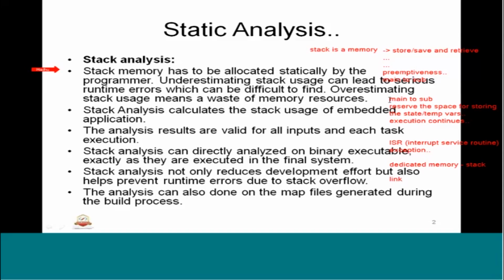We know that compilation and the linking are two aspects. As a result of linking, we know that object files are produced along with the map of the complete embedded system program. So there is a linker file which defines all the memory basically, but in particular the stack which we are of interest now. This stack basically will be defined in terms of how much the program is going to use.